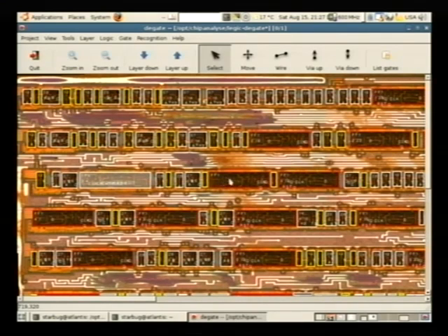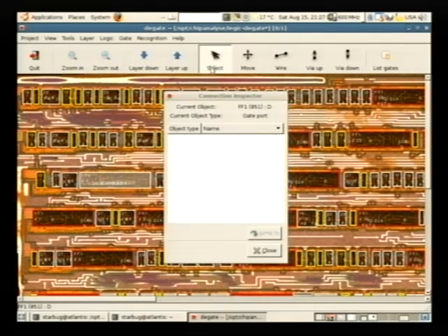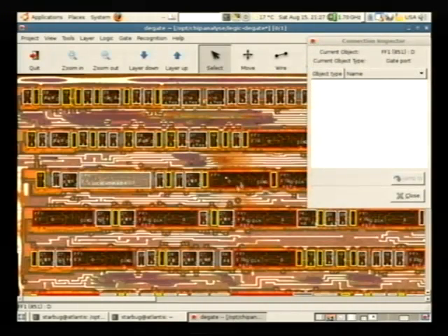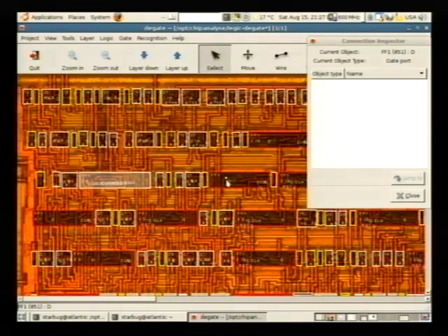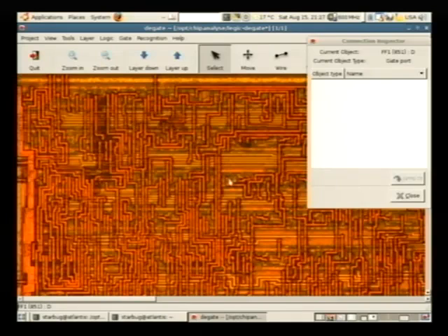If you want to know which port is connected to this D entrance of this flip-flop, you have to switch to the upper layer and follow the trace, going down again. So you normally have to do this on a big screen. And as you can see, it's still really complicated, so automatic metal tracing would be very nice.